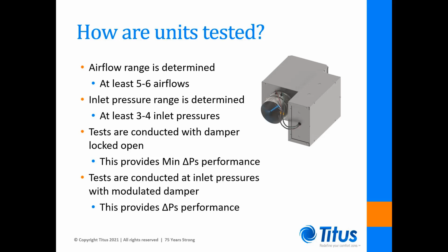We then linearize the data and determine the coefficients of a least squares curve fit. Now we have equations to accurately calculate the sound levels for a unit across its operating range for any flow rate and any pressure condition.